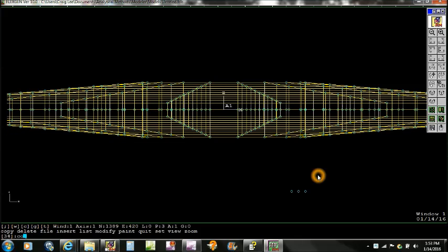I'll back up, zoom out, and now I want to copy those 3 nodes and do it 6 times going in the Z direction with an increment of 1 inch, and I'll create 18 nodes. So I'm going to do the same approach as I did on the disks there. I'm going to copy those and make a little tiny wedge there of the shaft.